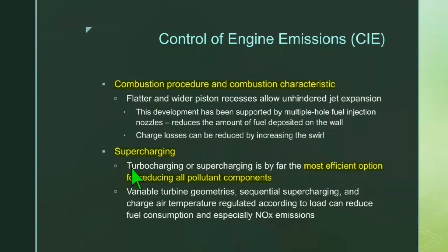Supercharging. Turbocharging or supercharging is by far the most efficient option for reducing all pollutant components. Variable turbine geometries, sequential supercharging, and charge air temperature regulated according to load can reduce fuel consumption and especially NOx emissions.